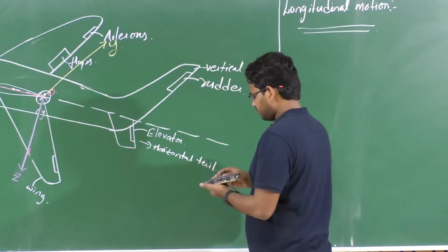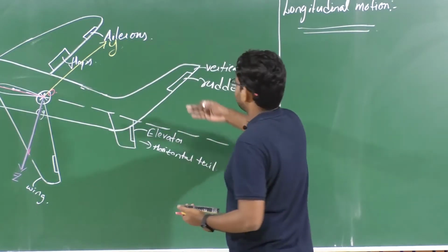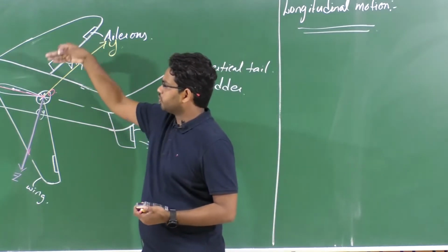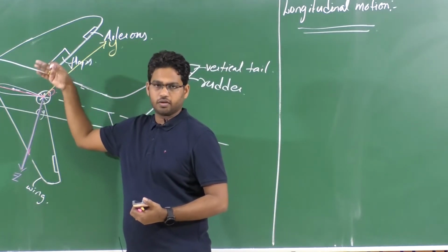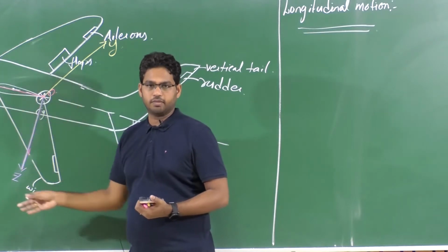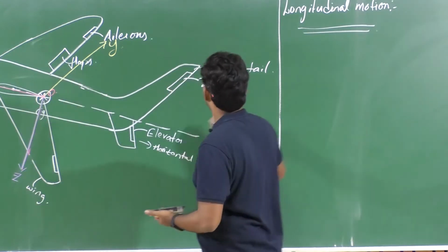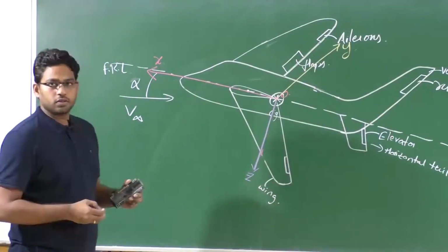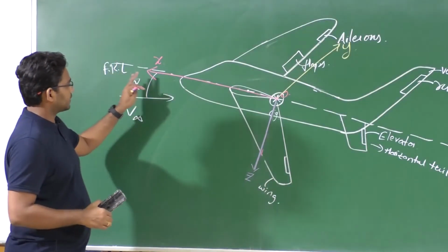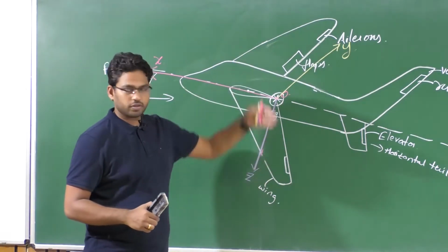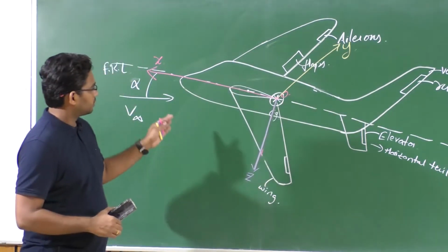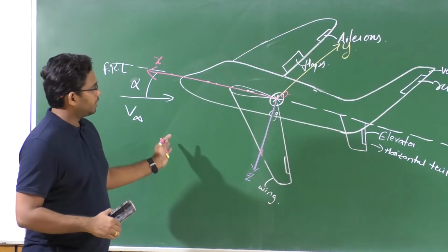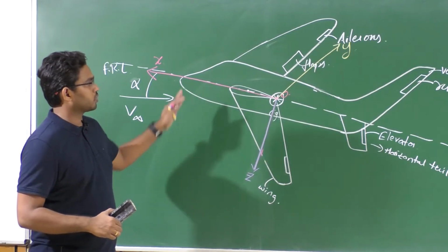Okay. So if the aircraft is moving in that particular vertical plane, or the motion is constrained to that particular vertical plane or the plane of symmetry, we call such a motion longitudinal motion, right? So the aircraft can translate along x-axis and z-axis, which corresponds to this vertical plane of symmetry, right? So there are two translational motions, and it can also have a rotational motion in this vertical plane.